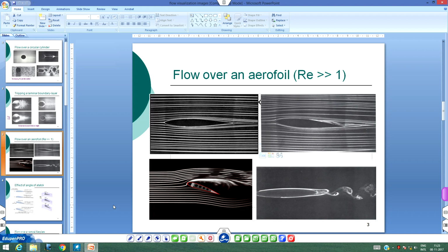So, you have a longish section on the side of adverse pressure gradient, so that the adverse pressure gradient is very weak and separation takes place much later. So, the wake is very narrow over there. Okay. This is with some slight increase in angle, the wake size has increased over there. So, these pictures are consistent with the discussions we have had.